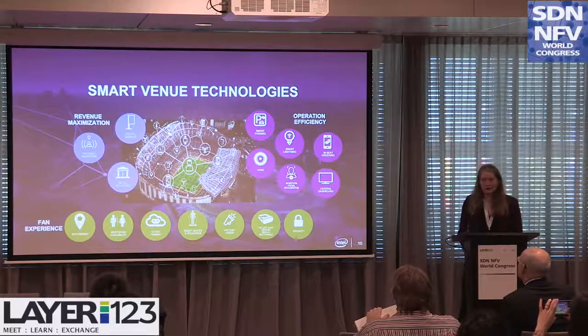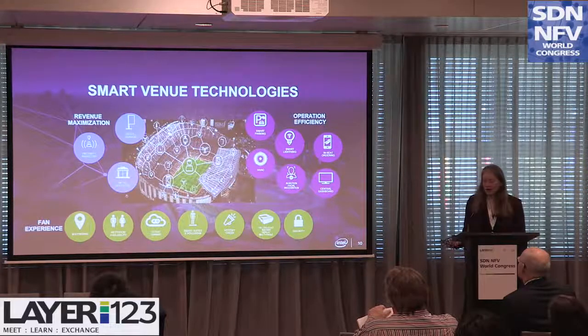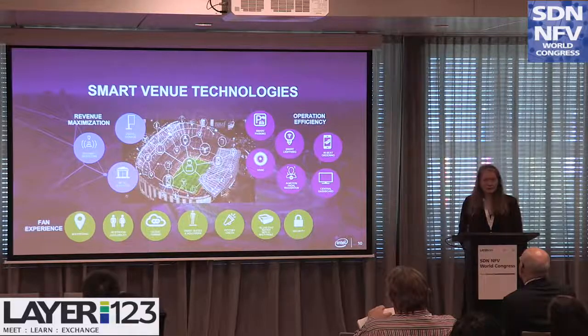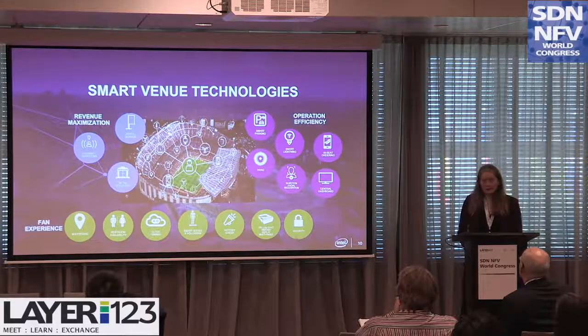Today, a lot of that fan experience is really about sharing your experience up on social media. So you get quite uplink-dominated data within this kind of smart stadium. But going forward, we really want to shift that to a more immersive experience. So maybe some kind of VR system and let the fans get playbacks from multiple angles. So we'd end up switching to a downlink-dominated data system. So again here, the view is that if we have a virtualized RAN, we can transition better over time, as we can allocate resources between the amount of uplink data and the amount of downlink data we're getting.